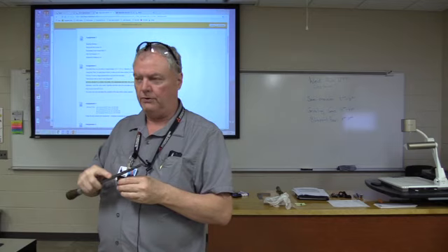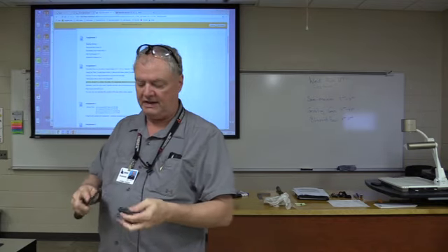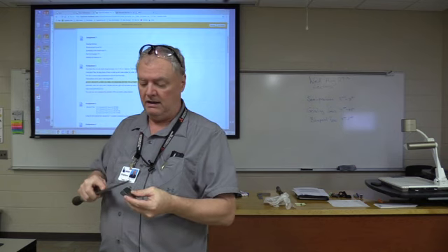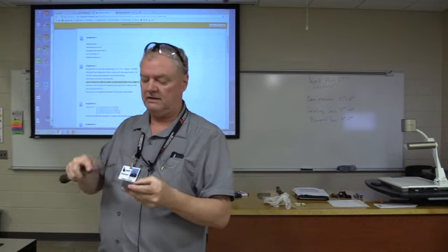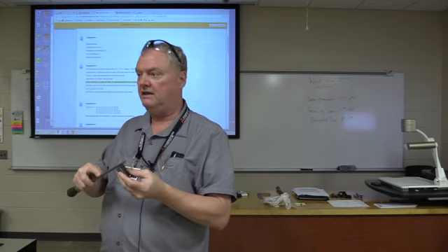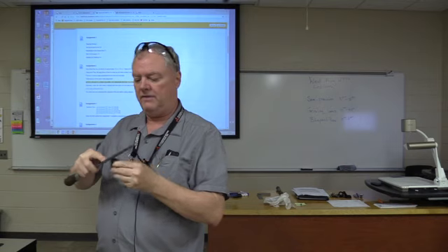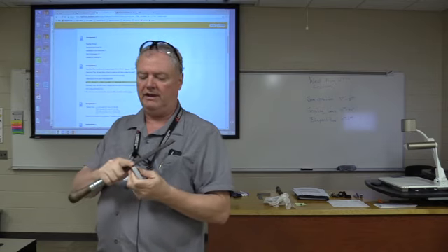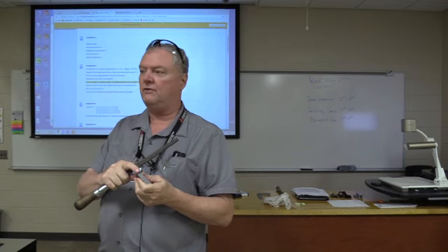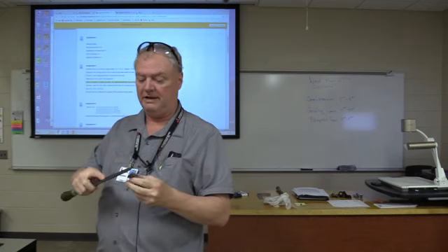Because the number one rule is you've got to have clean parts, you've got to have clean tables, and clean means not only are they removed of all grease and oils that have thickness, but the edges are clean, deburred, and then you'll be assured it will sit flat on a table. And all you really got to do is run your finger gently across a corner. You'll feel the burr right away. It's actually like a razor blade, very sharp.